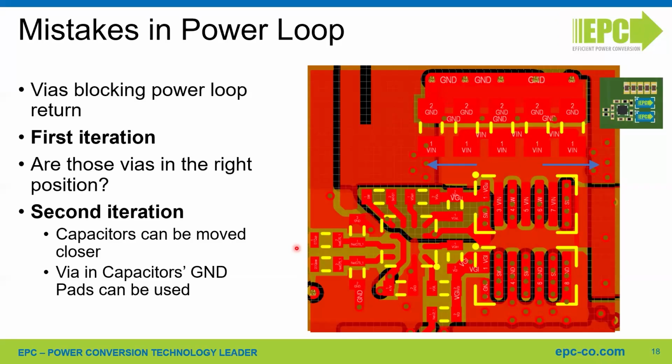If you add components in the gate, there is a chance that the improvements you can have with a diode and an additional resistor to speed up the turn off are compensated, let's say, by the additional parasitics that you are adding in the gate circuit. So basically, most of the times it's not worth using an additional speed up diode and resistor for the turn off.